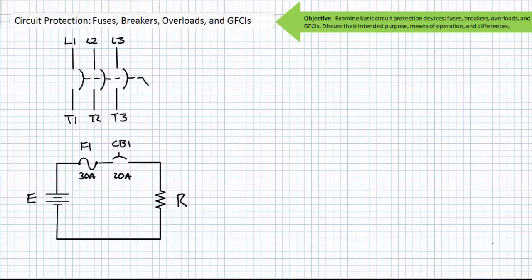For extreme cases, fuses and circuit breakers can both be paired in series with the element they intend to protect. In this case, the circuit breaker should have a rated current below that of the fuse. In the event of an overcurrent event, the reusable circuit breaker should trip first and open. If the circuit breaker fails to open, the overcurrent event approaches that of the fuse rating, which then melts. This double layer of protection uses the reliable fuse to back up the reusable circuit breaker.